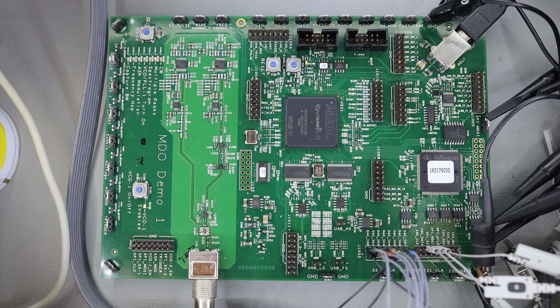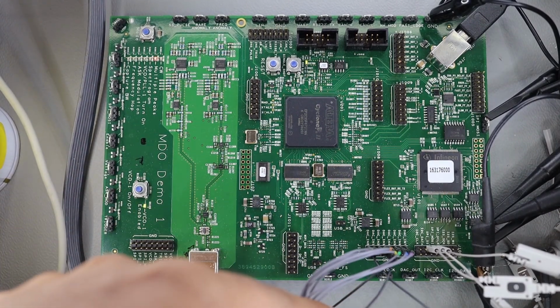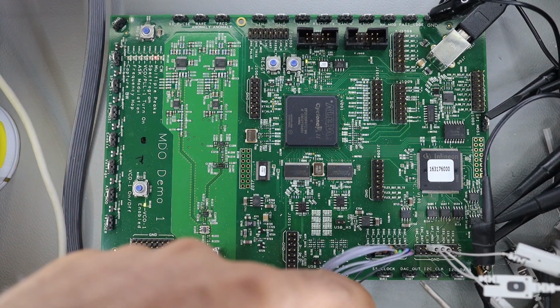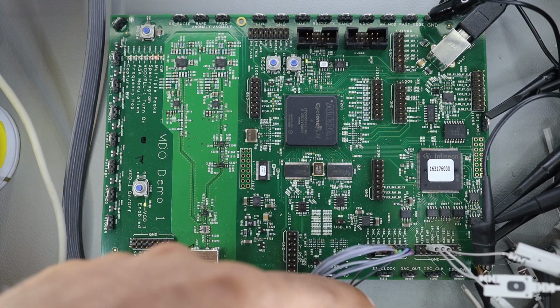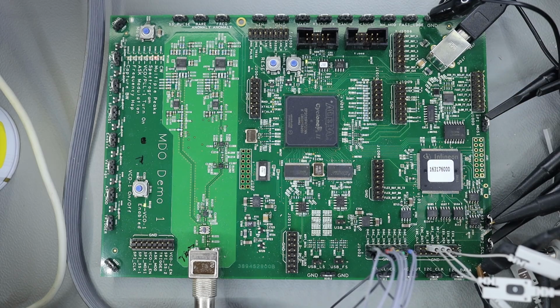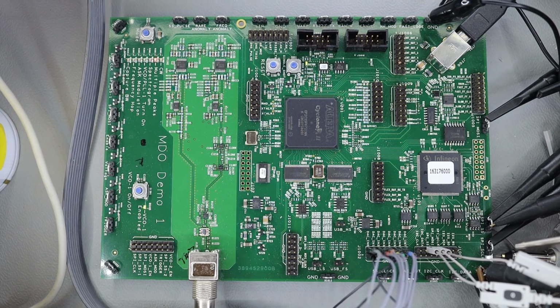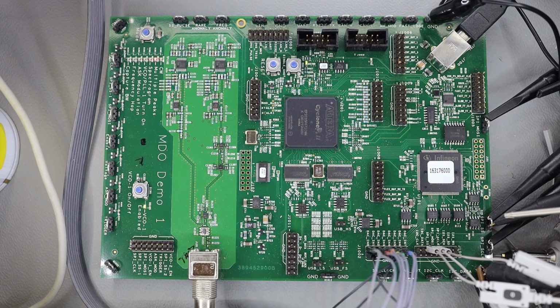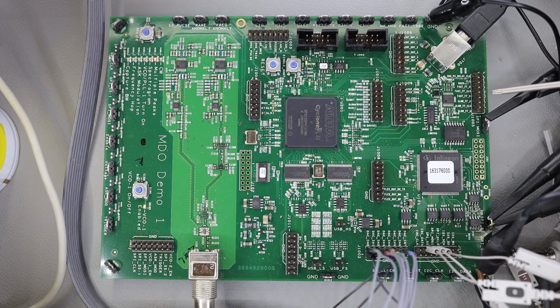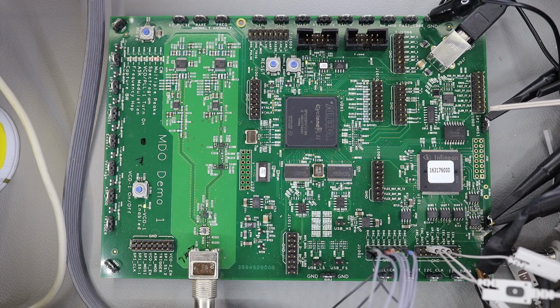So just to take a closer look at the board, the slow signals start from here, and you see that there is an SS clock, DAC output, I2C clock, I2C data, and on the right side, maybe I'll remove some of the oscilloscope probes, there is an SPI clock, SPI slave select, SPI MOSI, and there are some digital signals. There is a fast flip-flop clock, fast flip-flop data, slow flip-flop clock, slow flip-flop data, slow flip-flop Q, fast flip-flop Q, 300 picosecond delay, and primary clock.